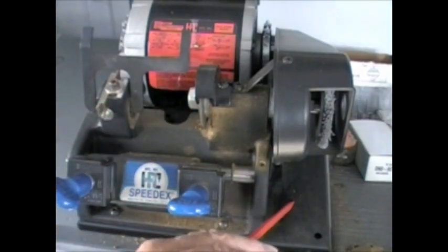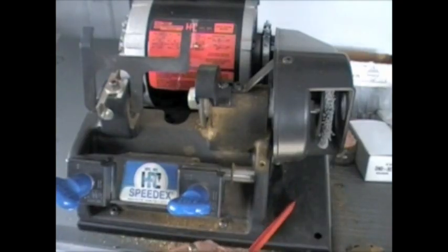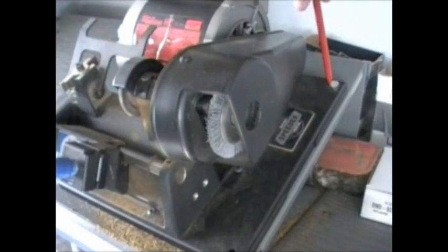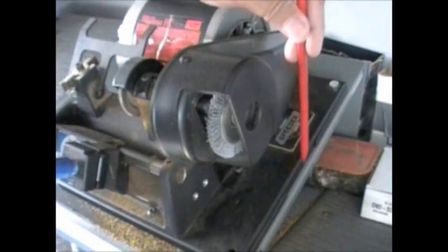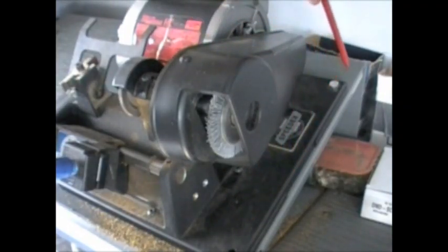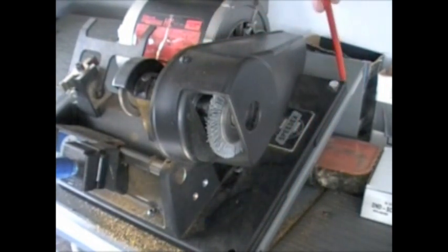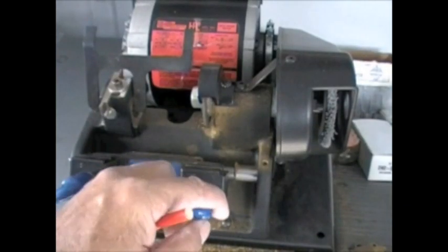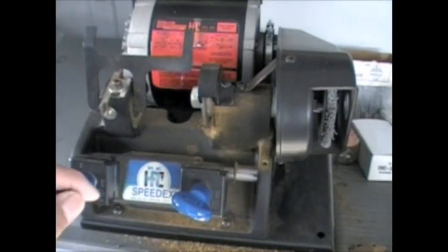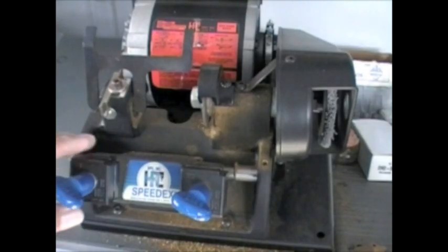The part that the key machine is sitting on is called the platform. Now the key machine has to be bolted down. This bottom part is referred to as the platform. You can see a bolt here, and you can buy these pieces of metal that are already angled to pretty much the right angle to support your key machine. These are the wing nuts that you're going to use to tighten down your keys. You want to tighten them down firmly, but you don't want to overtighten. A good snug fit is enough, you don't have to overdo it as you tighten down your key blanks and your keys.